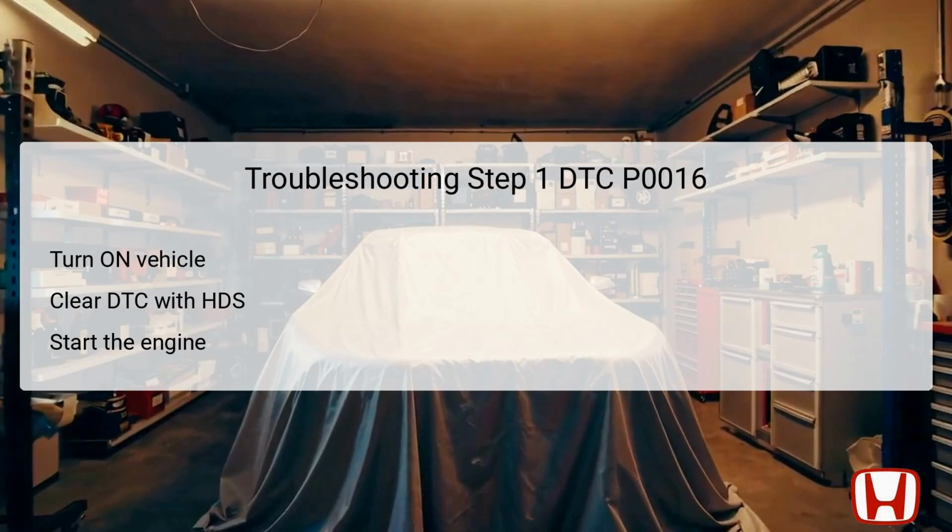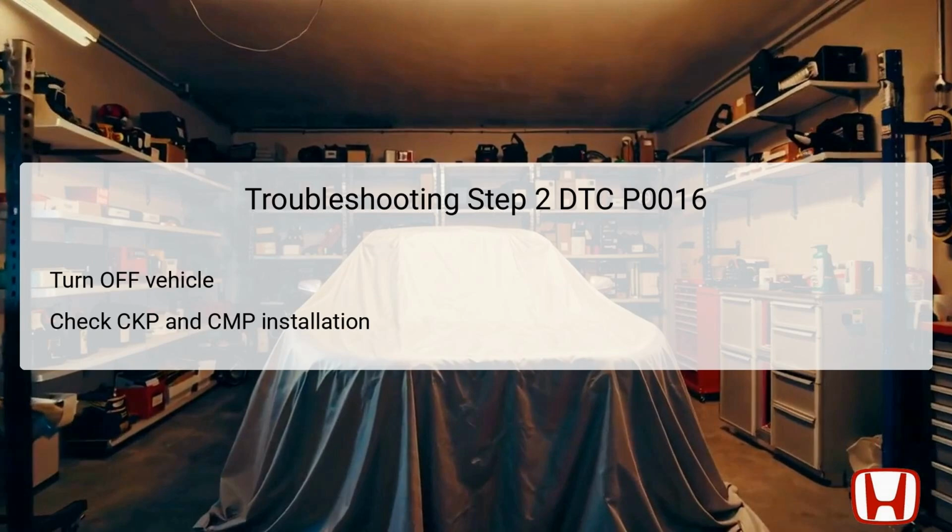Once the engine is running, you should recheck for any pending or confirmed DTCs using the HDS. This step verifies if the DTC P0016 is still present or if the issue has been resolved, which will dictate the next actions in troubleshooting. The second troubleshooting step requires turning the vehicle to the off mode to prevent any electrical hazards during inspection. Once the engine is powered down, the technician should carefully check the installation of both the CKP and CMP sensors.